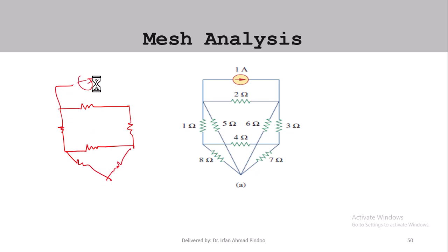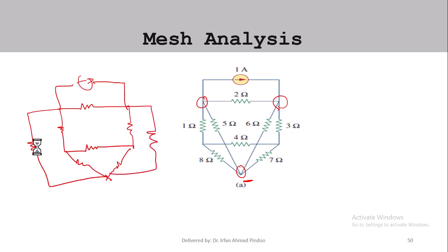The problem is in the resistors that are inside. So what we can do, because they are connected between these 2 points, and similarly here it is connected between this and this point only, so we can take them from outside like this. All right, like this. So this is this 5 ohm that was going from inside, and this is the 6 ohm. So if you now visualize the circuit, all the resistors are distinct, so that makes this circuit planar rather than non-planar.